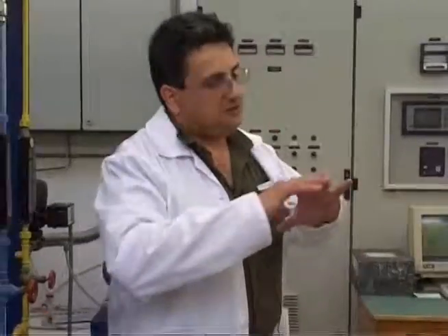The components are afterwards inspected and mounted into the furnace. The mounting, the positioning of the components inside the furnace is very important. Adequate space must be allowed for gas circulation around the component in order to modify the whole surface of the components.